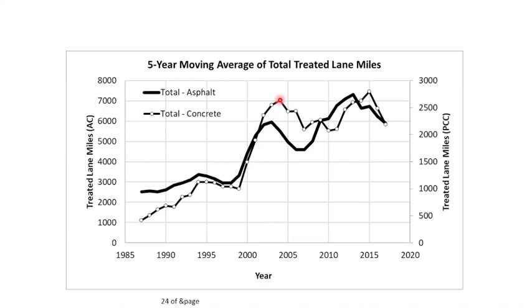And then before it drops, and definitely, see all these length miles lasted for many more years than this little short valley, right? That means PCC pavement, after you fix it, really lasts you many more years than the AC pavement before the next trend comes in, right?